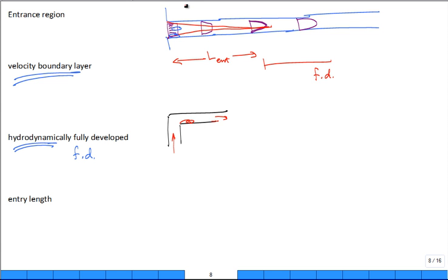And if you wanted to come in and do a takeoff on a duct over here or over there, being so close to that disruption might have a significant impact on what comes out. So a lot of times they'll have some rules of thumb, like after a major change like that, make sure you go down a long enough distance so it's back to fully developed or close enough to it.